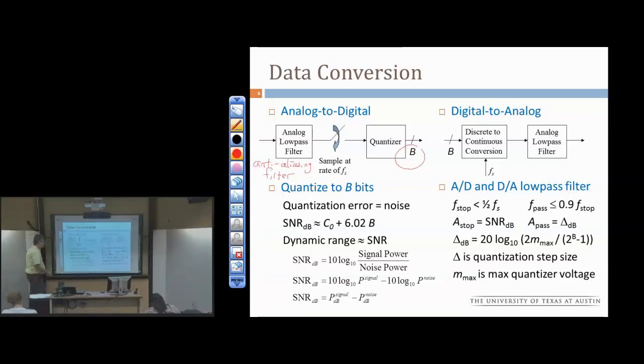In lecture 8, we analyzed the quantization error, same as the quantization noise. And the key in the system, what we'd hope to do is choose the number of bits to either meet or exceed the thermal noise that's in the system. If we don't use enough bits, then we end up having the quantization noise greater than the thermal noise, which we could do, but then we add more noise to the system, and that's usually not preferable. Sometimes it is, in odd cases, but for A to D conversion,